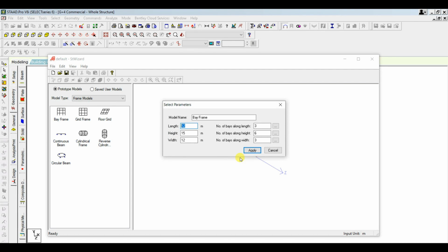We have 23.6 feet for each bay, that is 7.16 meter, multiplied by 3, which is 21.48. Along width also the same 21.48, and along height we have 4 meter each floor, which comes to 20 meter plus 1.68 as the foundation depth, so it is 21.68.